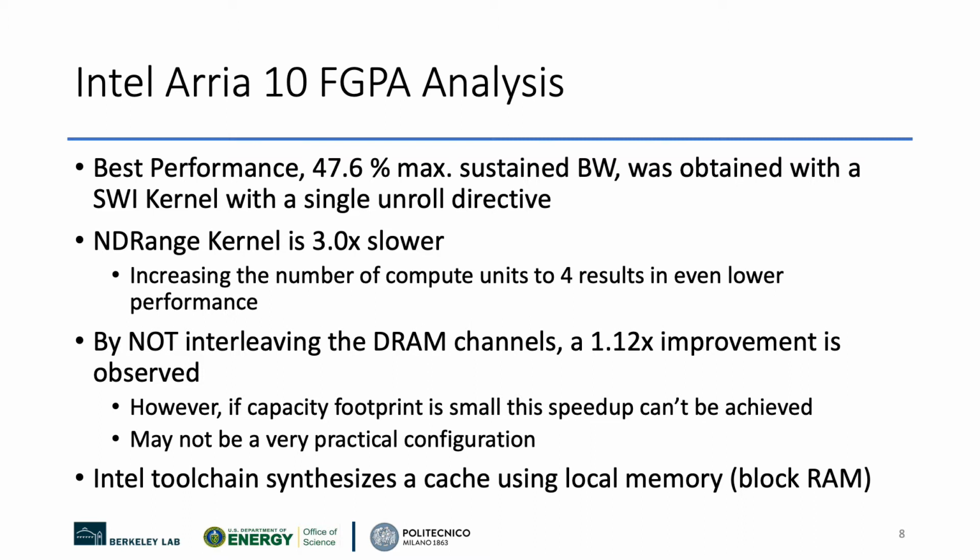The advantage of an NDRange kernel is the ability to define multiple compute units and hence to potentially increase the resource usage of the FPGA. But unfortunately, in this case, it actually slowed down the calculation.